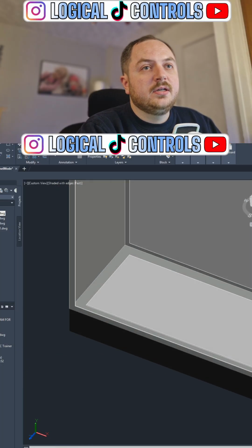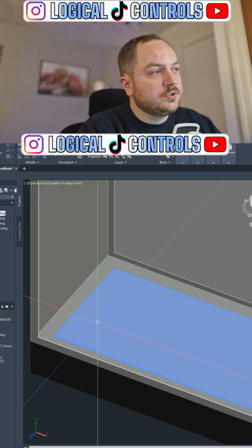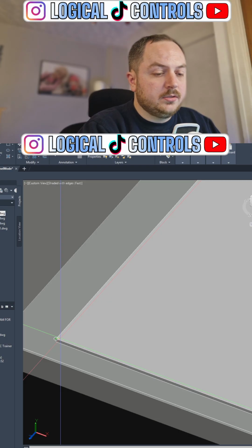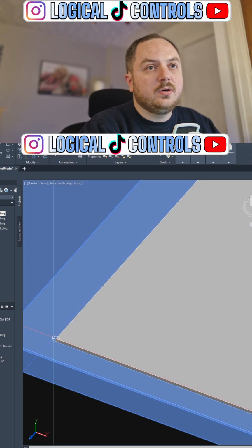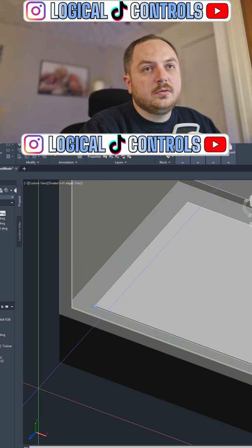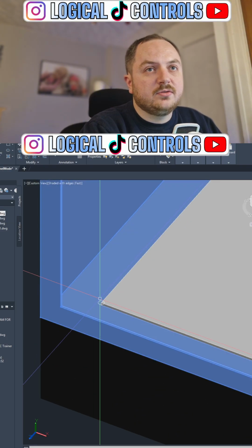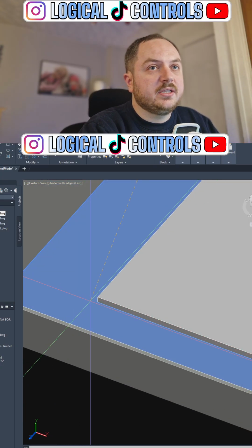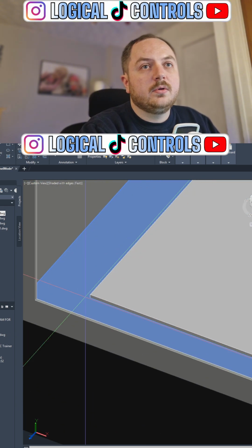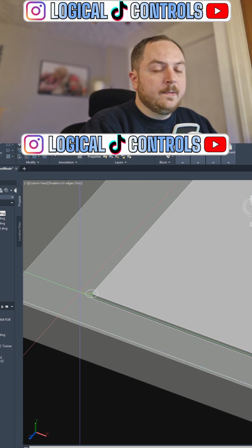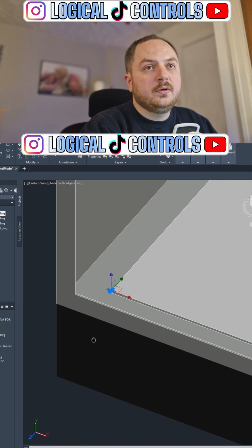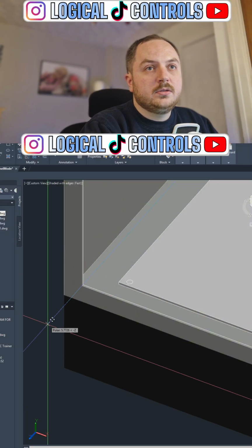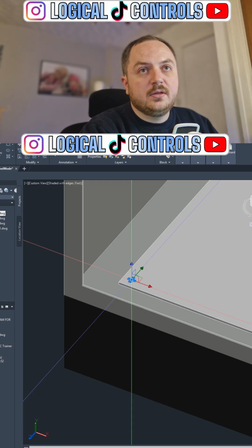How is that fixed? You would put holes in. I mean, I wasn't going to go into that level of detail, but we can since you've asked. Let's do some 6mm holes. And they'd probably be 6.5. In fact, I'll just make it 6.5mm, just for the sake of it. So then you could use an M6. Oh, that didn't quite work how I wanted it to. Then you can use an M6 bolt, 6.5. I'll put it in one corner. I'll take it in 10mm. Take it up 10mm. In fact, I'll just isolate this as well.